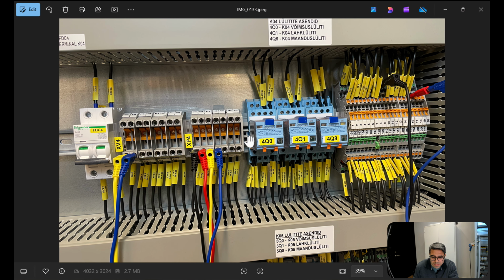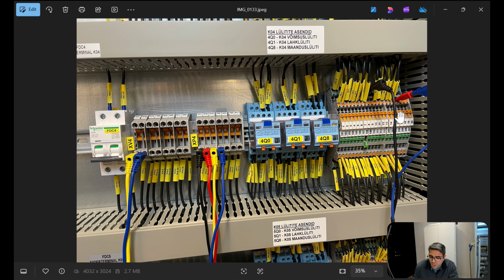And this is the fuse that, when you are doing anything around here, it's better to disconnect first. It should be green. Right now it's not connected. This is the fuse for this part. You disconnect this, and all of the power from this part will be disconnected. And every relay has one miniature protective fuse like that. So you put it green and then do what you have to do here. And when it's ready, then you connect this back.